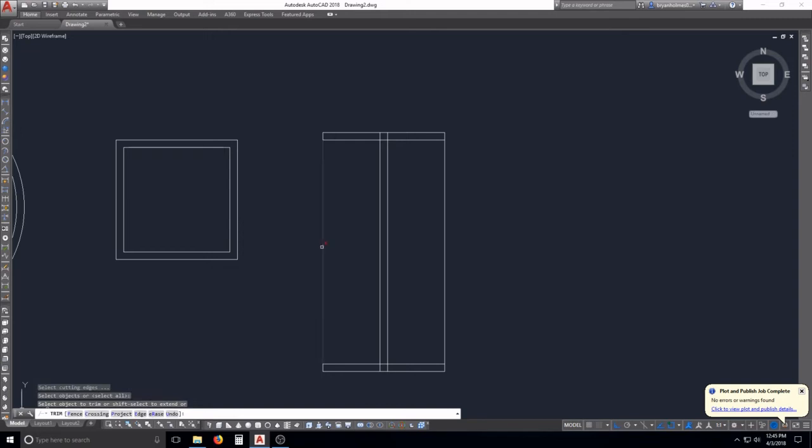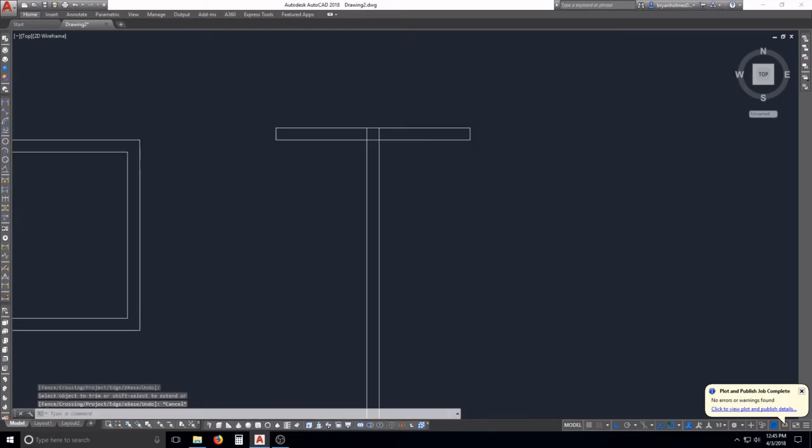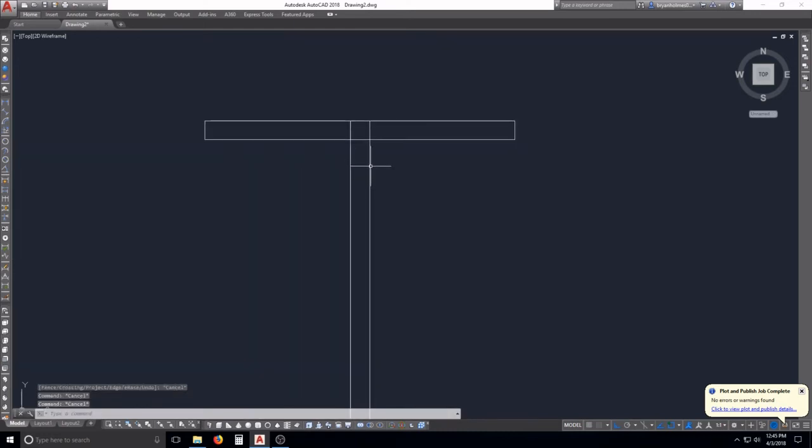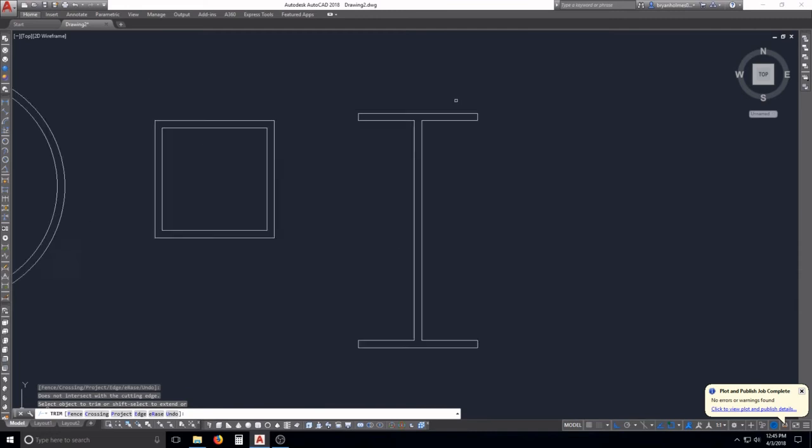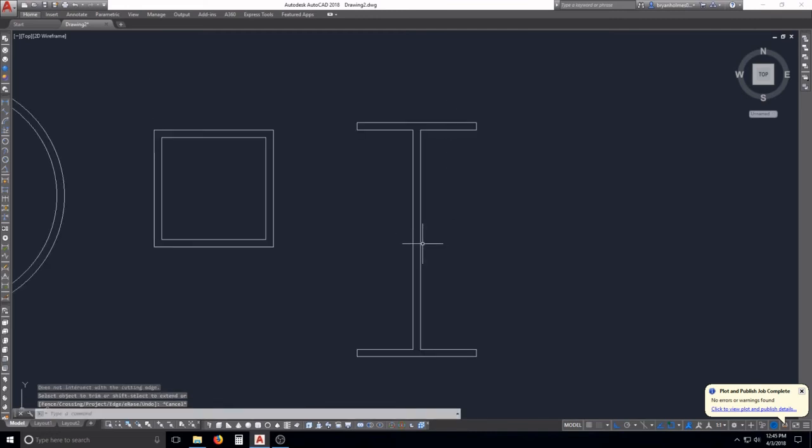and then we're going to right click and then left click and then left click. That takes practice getting used to that click order. I know a lot of people struggle with that initially. So it's TR, enter, right click, left click. After every preceding click, the thing you want erased would be a left click. Or you can draw a box around it. If you go this way, actually trim works either way. That's cool. Some commands don't let you go the other way. You'd have to have everything encompassed. But anyway, look at that. Looks like we're doing something now, guys.